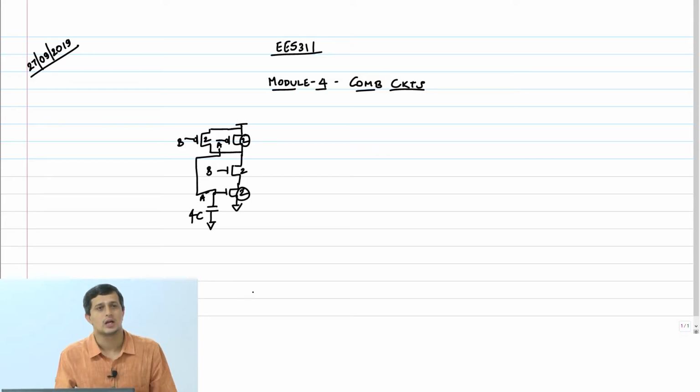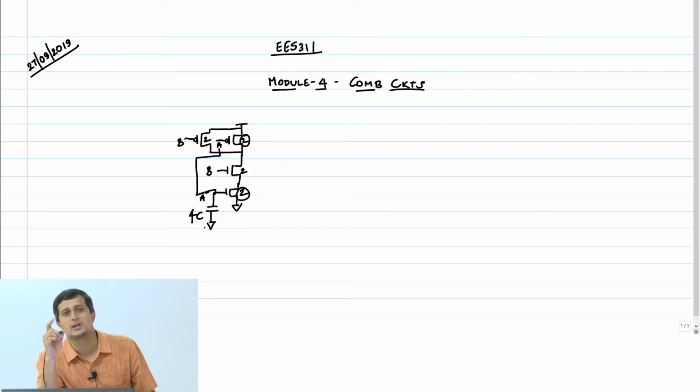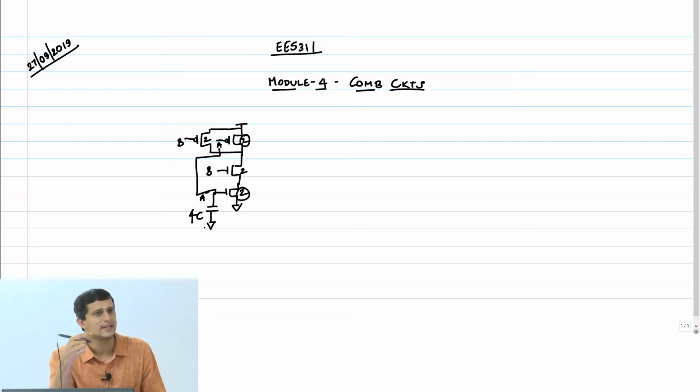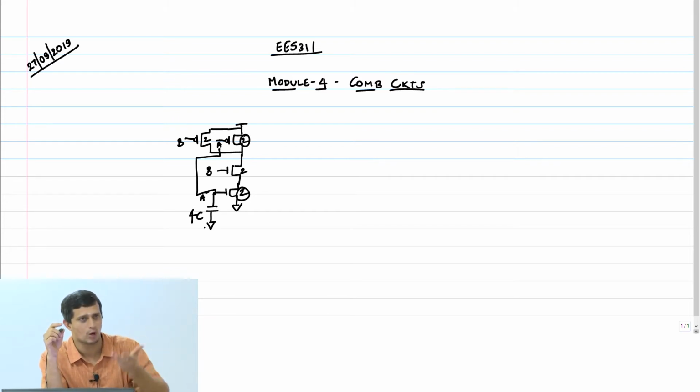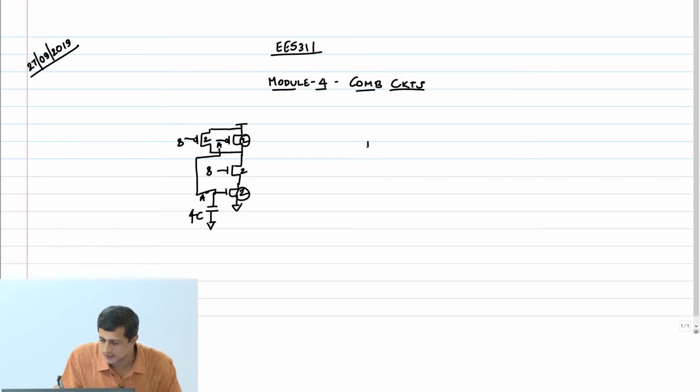Logical effort is defined as the ratio of input gate capacitance to the gate capacitance of a static CMOS inverter with identical drive strength. Because we have sized the NAND gate already to have 2, 2, 2, 2, making sure the resistances are the same, our reference inverter is just the standard reference CMOS inverter, sized 1, 2.